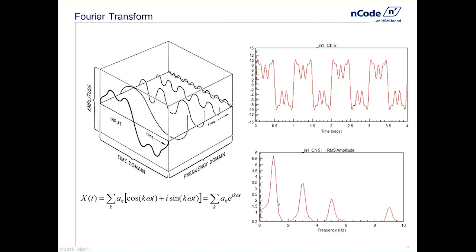These are very pronounced, unique, discrete peaks, whereas the PSDs we will typically look at might be more broadband. They might have a lot of frequency content in between the peaks. That's something that we would probably see more often with real measured data. But this is a really good representation of how that Fourier transform can go from the time domain to the frequency domain.